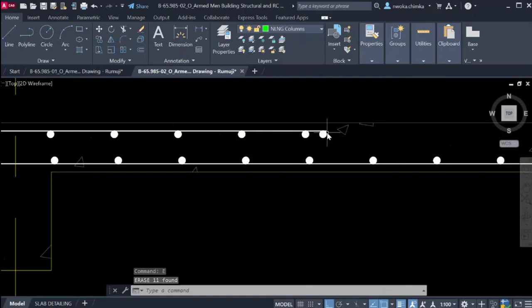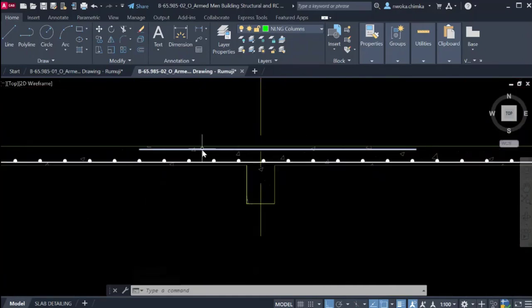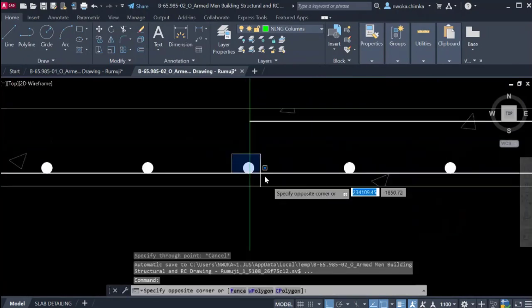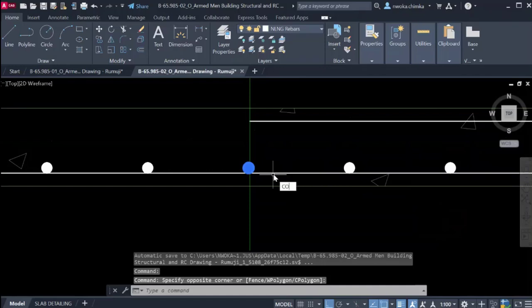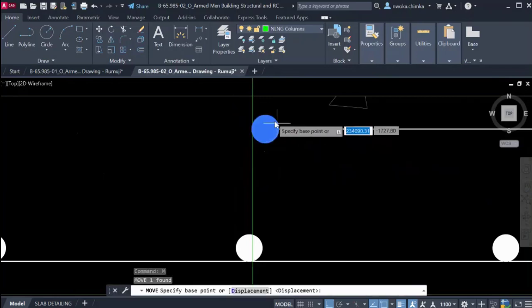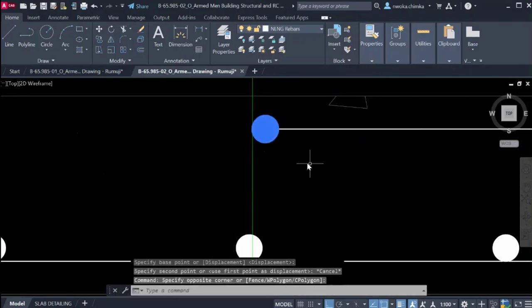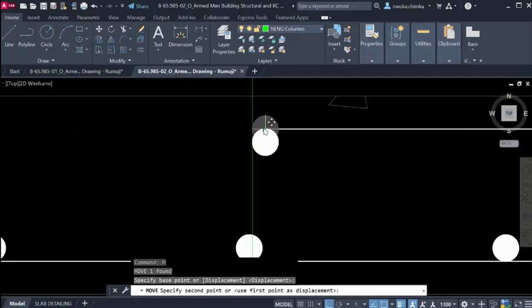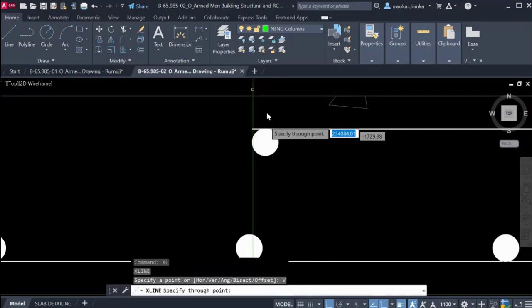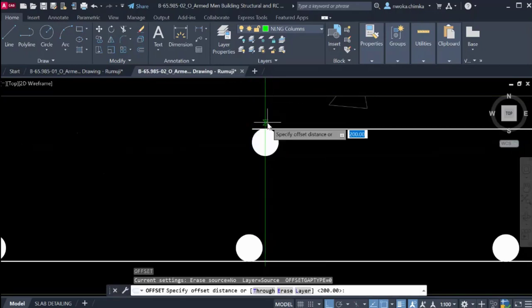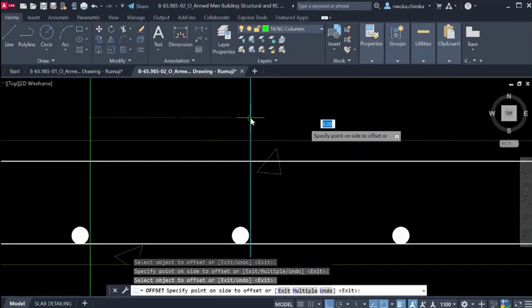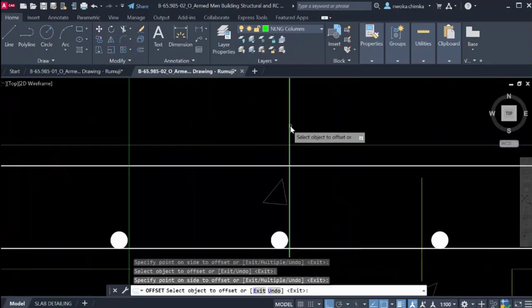So this is what we will now have right now. Next thing we'll do is to do the same for this. So we go again XL vertical, which is this, to base to this point, and click on this using the copy command, and then pasting it here and bringing it down to align, to flush with this distribution bar. So flushing with this right now, then removing this construction line, creating a new one, V, enter vertical to then offset 200 millimeter and begin to offset 200 millimeter all the way down.